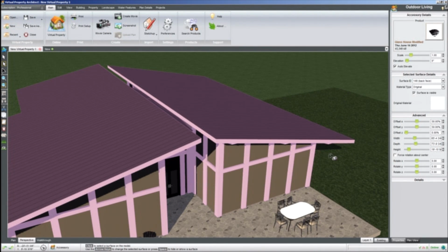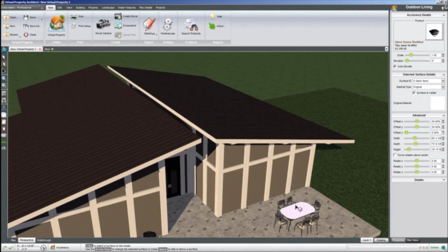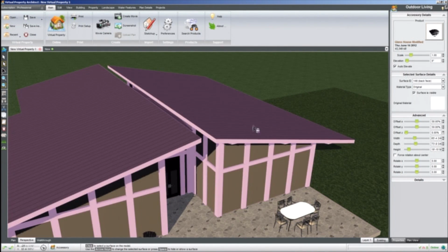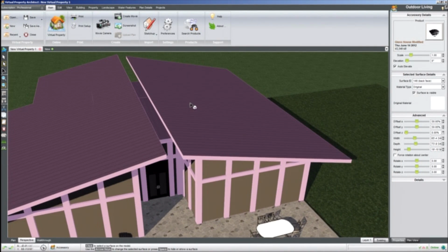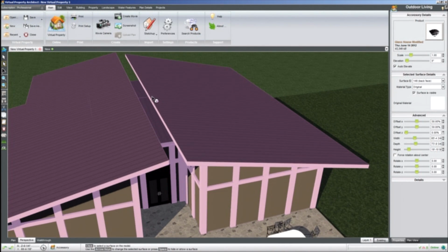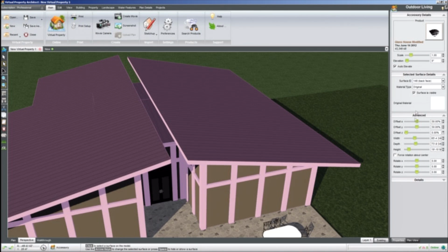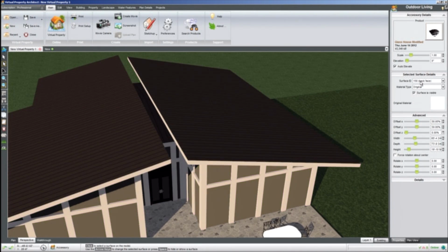You may have noticed it switching numbers back and forth as we select different materials in the scene, and we can see almost everything here is a back face. So this is a pretty wild model. If we wanted to get to this roof material, and we absolutely had to work with it in this state, with no time to go back and clean it up, maybe because we'd already configured half the materials, we can select this menu once and then use the up and down arrows to tab through different surface IDs.